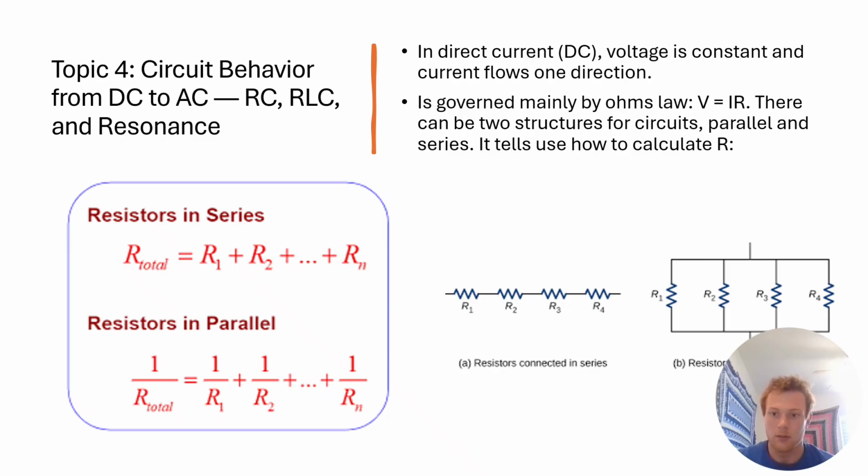Since it's set up like one row after the other, that's going to be in parallel. And so we use the resistance rules for parallel. We do 1 over 1,250, and we add that 140 times because there are 140 rows. And since it's 1 over, we have to flip it over, and it's going to be 1,250 over 140, and that is our resistance. And so I equals 750 over 888. I think this problem demonstrated how DC circuits work and how you have to think about them with the resistance.